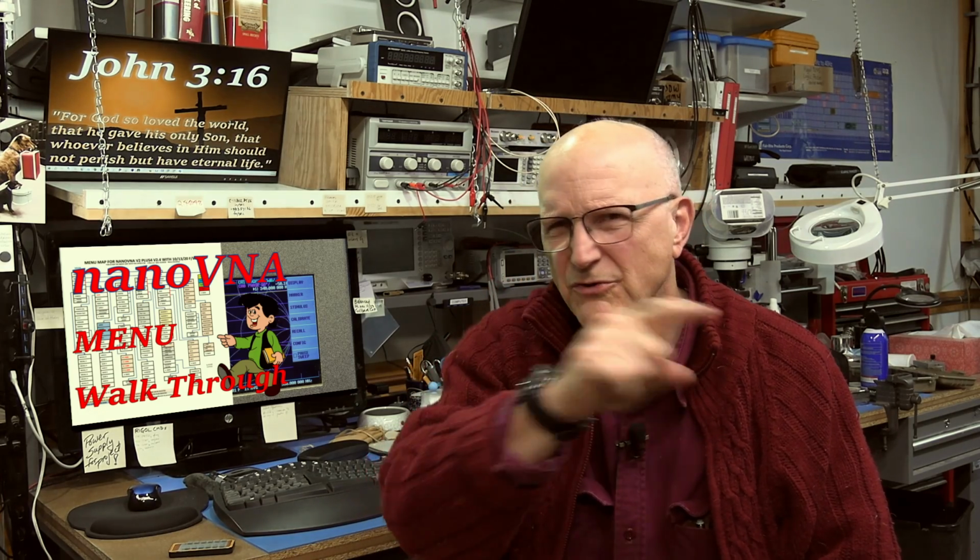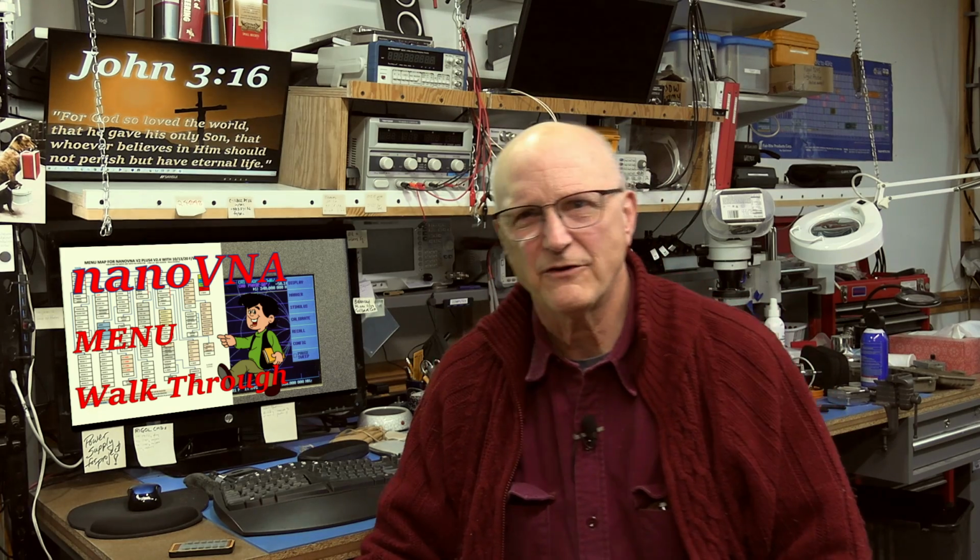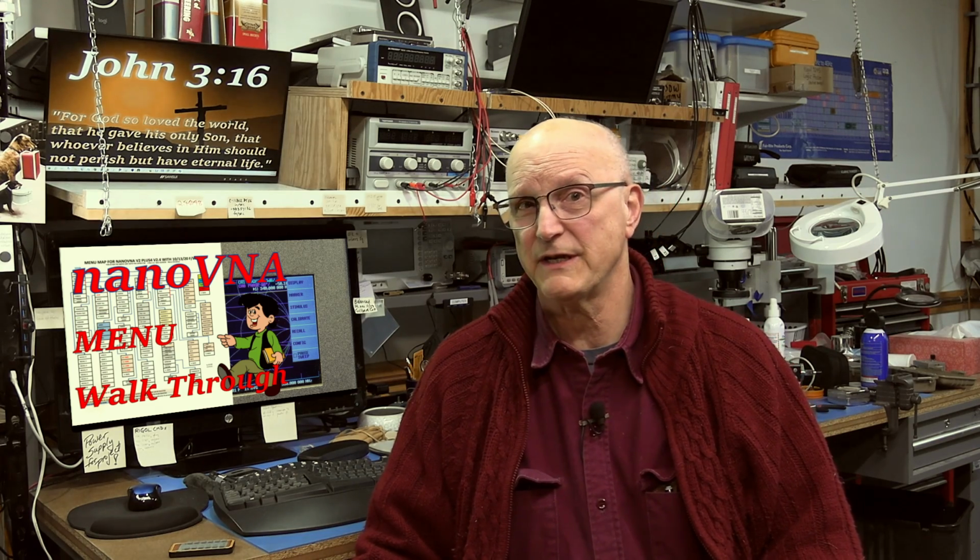Now, let's just say that we have all this laid out. We've got a plan. Now what? Well, the next step is actually up to you. You could configure your nanoVNA to display what you're looking to see first, or you could configure your nanoVNA's frequency ranges and the like to cover the frequencies you're interested in.